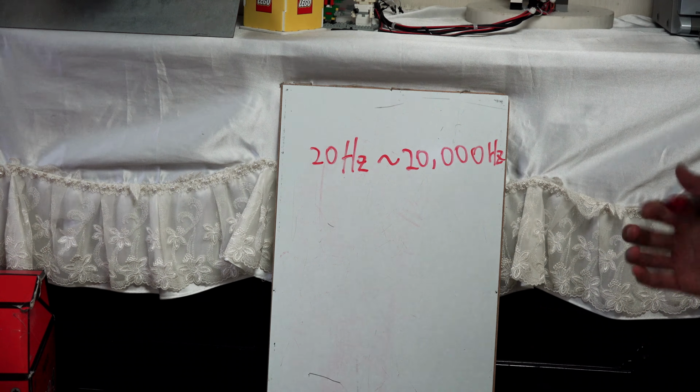We know the duration, and we want to find out the distance. So all we have to do is find out the speed. As you know, the speed of sound is 340 meters per second, which was found by scientists. So we know the speed and we know the duration from the sensor, and then we can find out the distance.